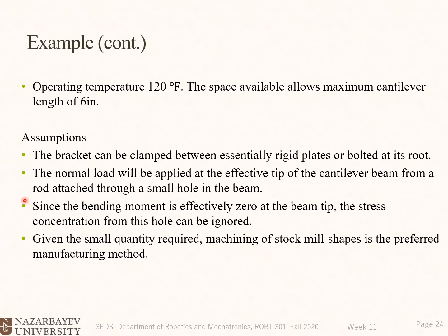Since the bending moment is effectively zero at the beam tip, the stress concentration factor from this hole can be ignored. Okay, so this is a stress concentration factor at the tip of the beam, not at the root of the beam, not at the big support. These are the assumptions that we are taking. Given the small quantity required, machining of stock mill shapes is the preferred manufacturing method.